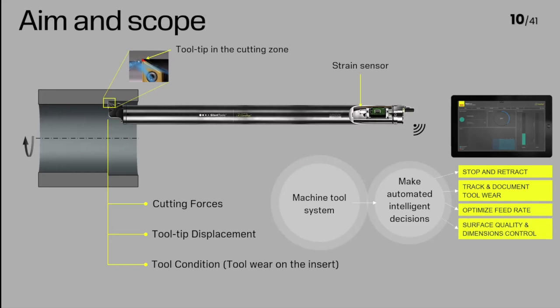And we can monitor the surface quality and the component dimensions during machining, reducing scrap and rework. And we can even estimate the remaining tool life and adjust the process accordingly to maximize the productivity. So instead of passively collecting data, this sensorized cutting tool becomes part of a smart and adaptive system, driving the performance and process reliability from within.